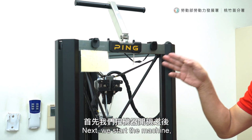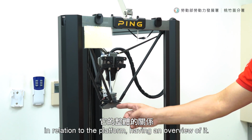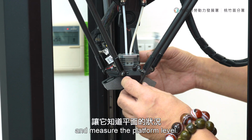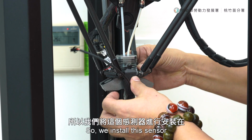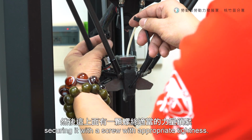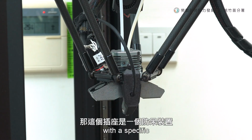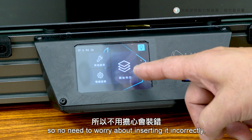Next, we start the machine, adjusting the height of the nozzle in relation to the platform, having an overview of it. We use the sensor to detect and measure the platform level. So we install the sensor at a fixed position on the nozzle, securing it with a screw with appropriate tightness. It is also plugged in with a specific foolproof orientation, so no need to worry about inserting it incorrectly.